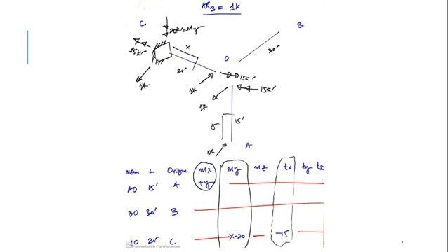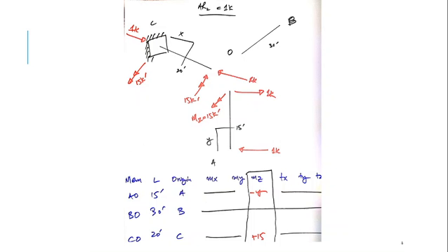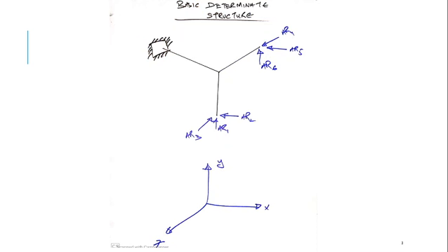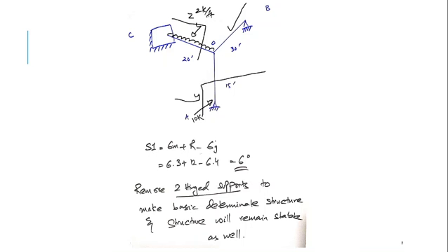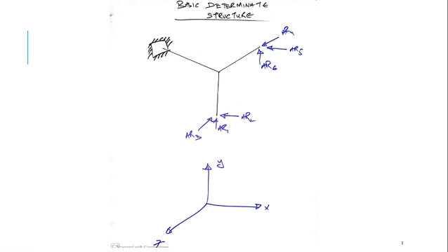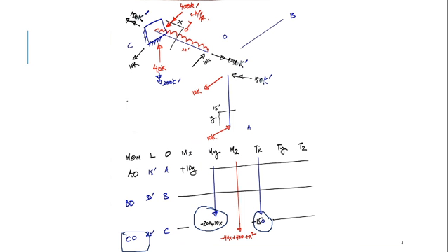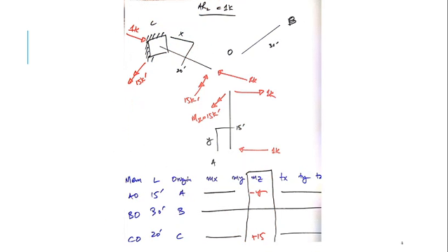Using the same basic approach of how to solve a beam or simple frame by the flexibility matrix method, you should identify the redundant actions and make it determinate. Then you have to develop the DRL matrix, then the flexibility matrix. Then using the first mathematical model, you will calculate the AR matrix, AM, AML, and finally the shear force and bending moment diagrams.